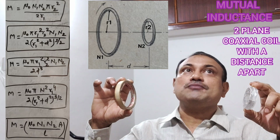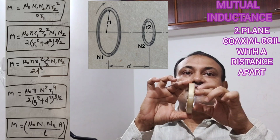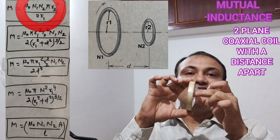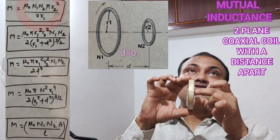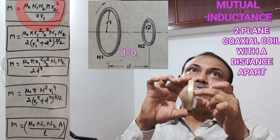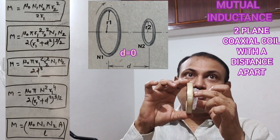In the same way, if d, the separation between these two coils, is equal to 0, that means they are coaxial with both centers merging together. In that case, the formula reduces to mu 0 times n1 n2 pi r2 square by twice r1. This is the formula for a two-coil system at different separations.